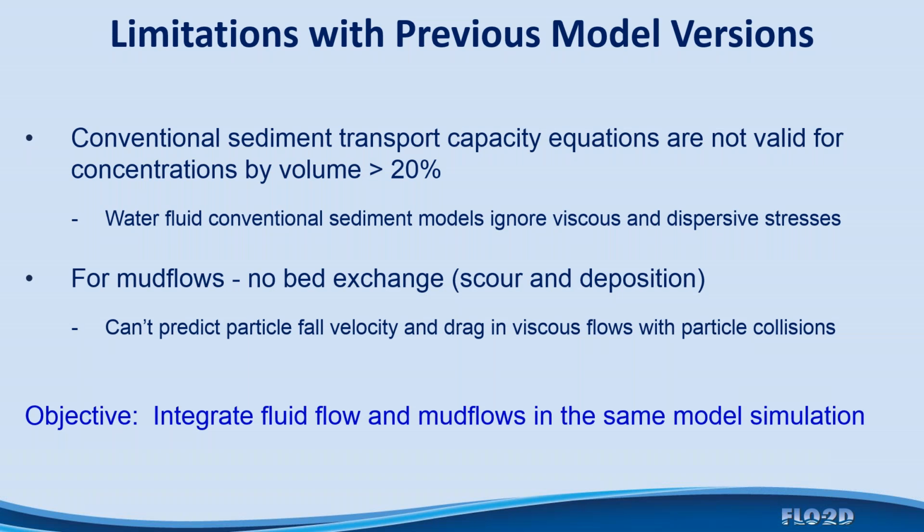On the other hand, for mud flows, if you were to model only mud flows without water, just hyperconcentrated sediment flow, there's no exchange with the bed. That is, it's just a flow that would either cease flowing and be remobilized, but there's no bed exchange. There's no scour and deposition. And the reason is that you can't predict the fall velocity and drag in viscous flows with particle collisions. Nobody's really done that, as far as I'm aware, so that it has practical application in a fluid model.